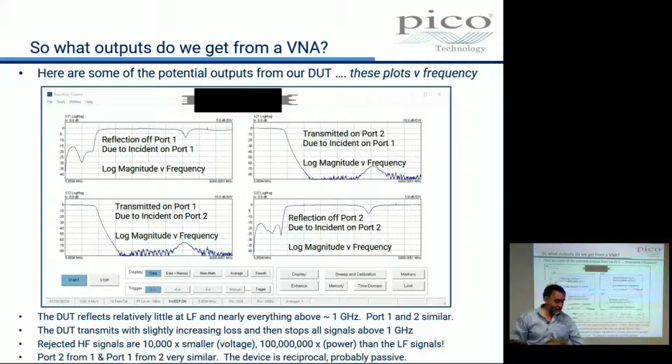So horribly mismatched. Do we know what that is yet? What is it? It's a low-pass filter. It's a low-pass filter with an AC coupling. You remember the scope found that down at low frequency it was AC coupled. Yeah, so I actually put a DC block capacitor. That's the 220 nanofarad capacitor that the DMM measured, right? So we do know what this thing is now.